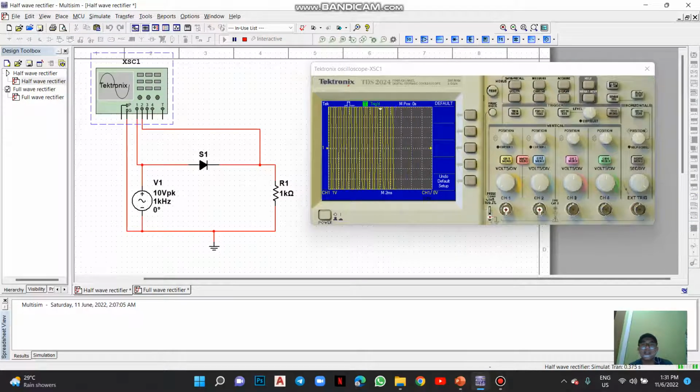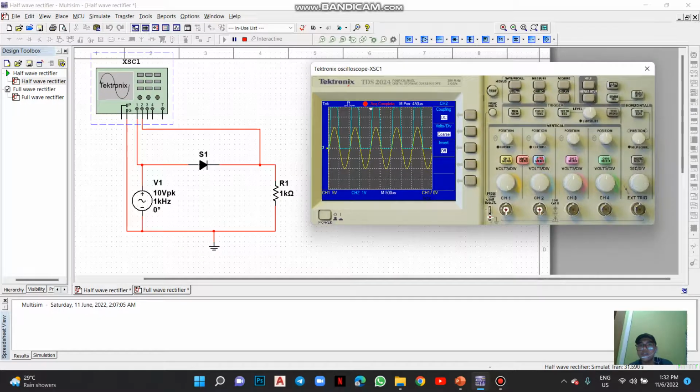So as you can see here, this is our waveform, which is the input signal. We zoom in first, and then we change the volts per division to see the voltage value clearly. As you can see here, for the positive cycle, we got a value. If we measure it, the V maximum is 9.98 volts, while for the negative cycle, the V minimum is around negative 9.98 volts. And if we run it again and set channel 2, and then change the volts per division,